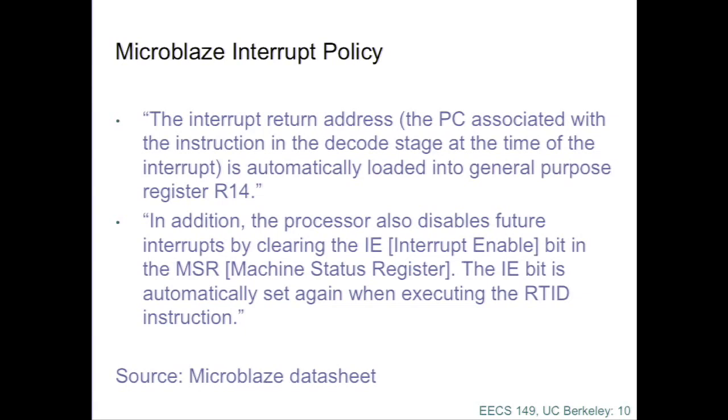Okay. By the way, the compiler hides a lot of this from you, and I'm going to talk about that today because it's awfully tempting to use this Harry Potter style of programming where you just look up the magic incantation to make stuff happen and stick that in your C code. But it's not good enough, generally, for embedded systems. Certainly not for safety-critical systems. You'll never get away with it for safety-critical systems. You've got to know what's going on in those magic incantations. And if you need to control timing, you need to know in quite a bit of detail what's going on.